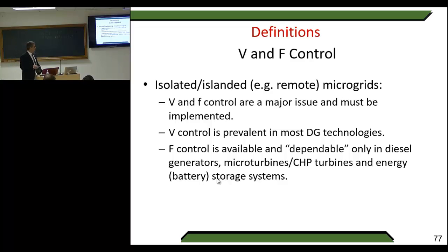We are working a lot with some of our colleagues, Claudia, on this derating of PV to provide ancillary services like emulation of inertia, or more than that, to support the system with some control strategy. These are things that today are more common to see. Last week in Chile was the first trial by Laborelec, by ENGIE, of the first 100 megawatt photovoltaic plant in Chile. They tested the frequency control of the power plant with a derating of 30% compared with the MPPT, and the results are very interesting. They support the main grid. It's not a microgrid.